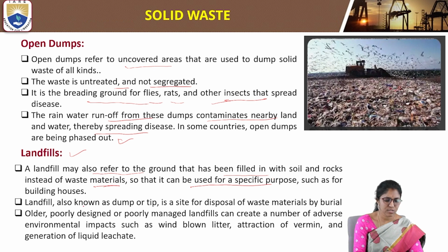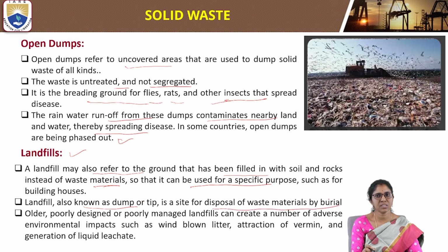A landfill, also known as a dump or a tip, is a site for disposal of waste materials by burial. Older, poorly designed or poorly managed landfills can create a number of adverse environmental effects, such as wind-blown litter, attraction of vermin, and generation of liquid leachate.